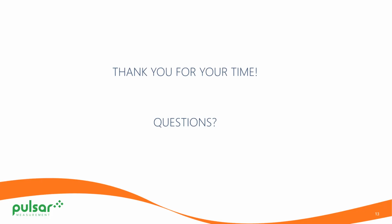It says, good day. Regarding the last question, transit time should be better for a corroded pipe or Doppler. I think that's a tough one to answer. And the reason I say that is you've got to throw the process fluid into the equation. If all things being equal, I would say there isn't much difference. I will say the Doppler sends a lower frequency. So it can fight through pipe corrosion and thick mortar linings better, maybe, than a transit time. But your ultimate decider will not really be the corrosion. It would be really, is it a good application for one or the other?